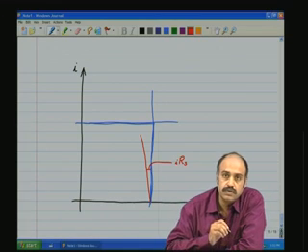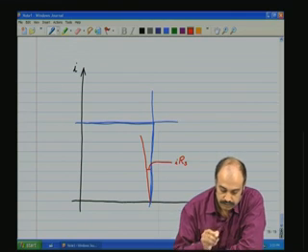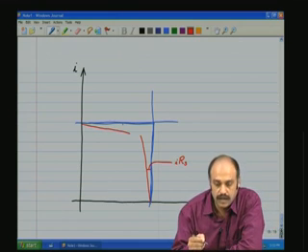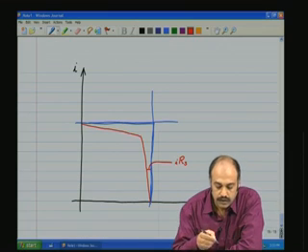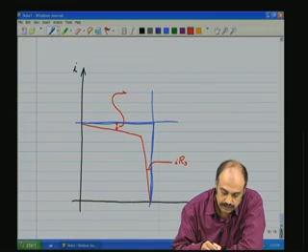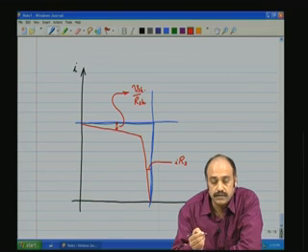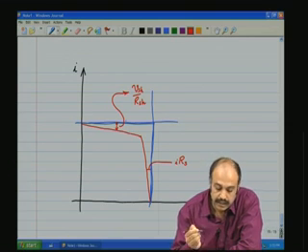The shunt resistance is going to affect the current source parameter. So, because of the shunt resistance, it is going to deviate from the horizontal current source effect due to the non-idealities of the R shunt, and that is V by R shunt, where V shunt is the voltage across the R shunt. So, to that amount, that much current keeps decreasing.